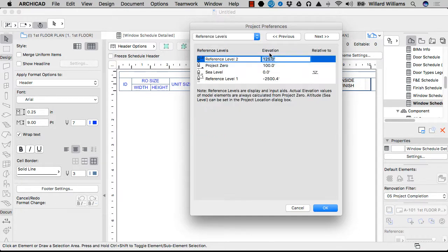And then you have reference levels. In here you would adjust the height and the basic information that you would use to set up your project from the start. And I recommend figuring out where your building is, or where it should be, before you get started, because it can affect the way walls and information will show up, and it's good to set it up initially.